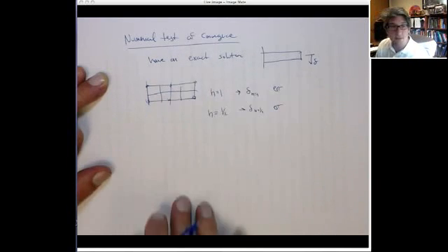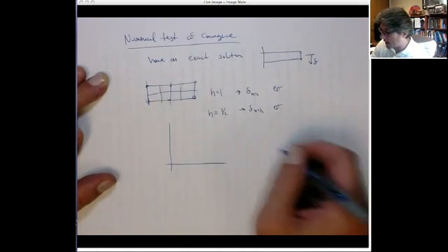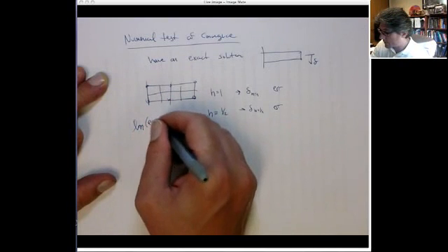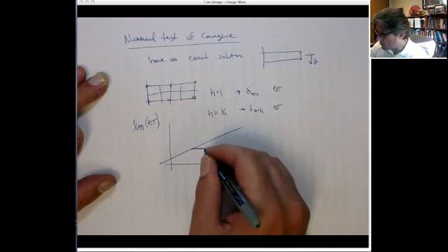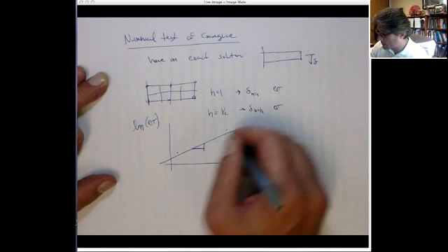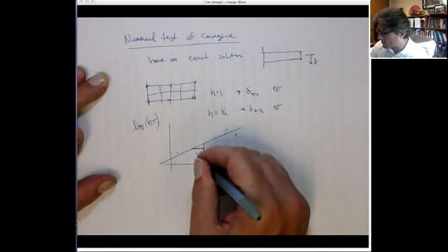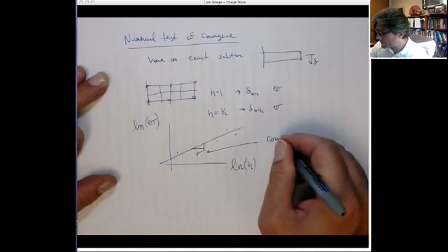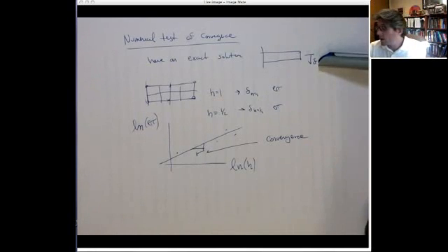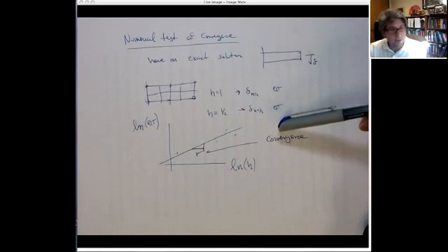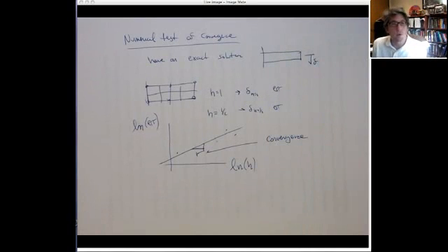And you can keep dividing elements, right? And then you can actually make the plot, the log of the error versus the log of the element size, and you can then get the slope. So you actually would plot discrete data points. You could actually get the slope. So that slope is your convergence. All right? So if you plot the error in displacement, that's going to give you the convergence in displacement. Now your convergence in stress will most likely be one order less than that, so you can subtract 1. Or if you have a result where you know a stress, you can plot the convergence for stress, and your displacement convergence will probably be one order higher than that. So you can actually numerically test the convergence.